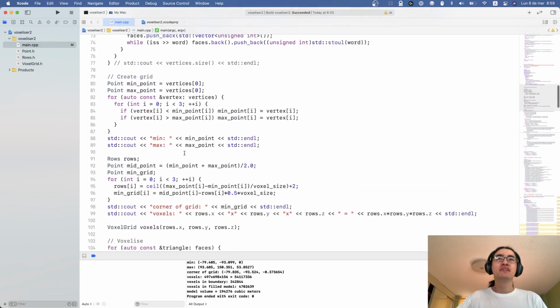I just did a very quick solution for this. I recentered the model, not to be perfectly aligned to the minimum of the bounding box, but I actually centered the mesh on the voxel grid. This is generally a good idea because it produces nicer looking voxel models, and you are not dealing so much with edge cases.